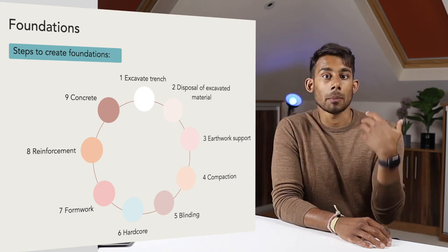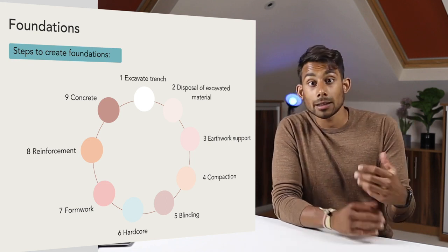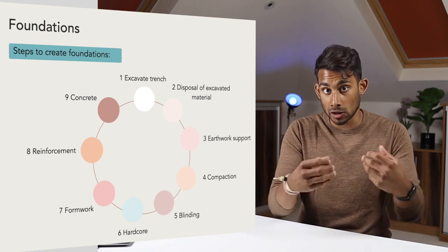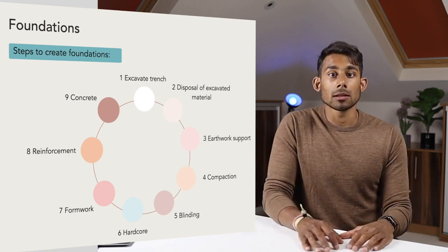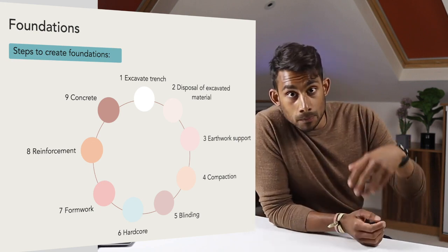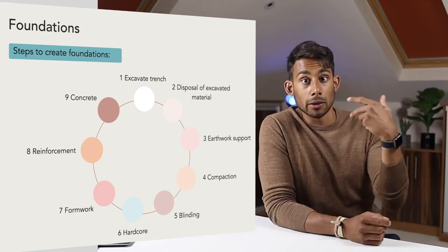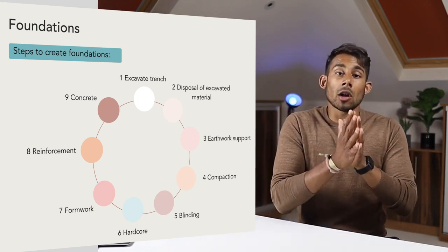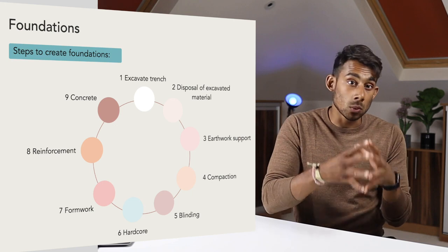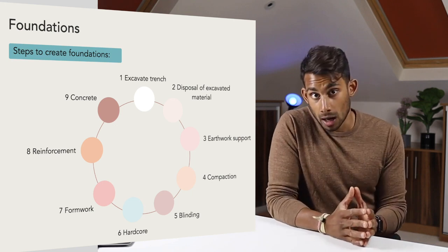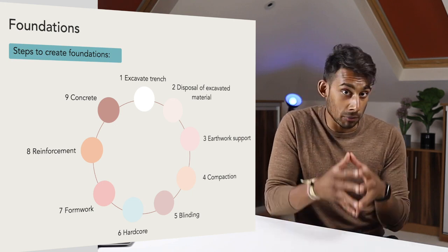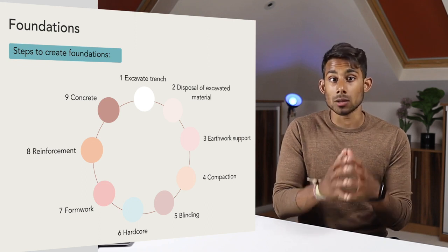When the surface is compacted to the marked out level, it can be smoothed and leveled with a conventional hand float. It's important to make sure that there is enough room on site for the delivery truck. They are around 9.5 meters long, 3 meters wide and 4 meters high, with a turning circle of about 17.5 meters, and they weigh up to 32 tons.